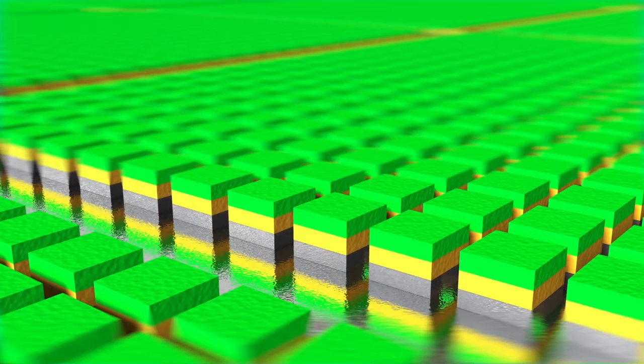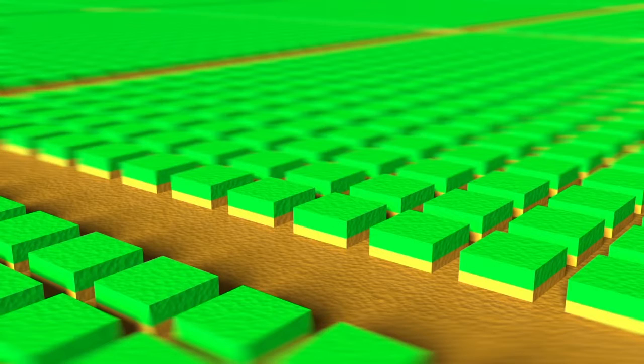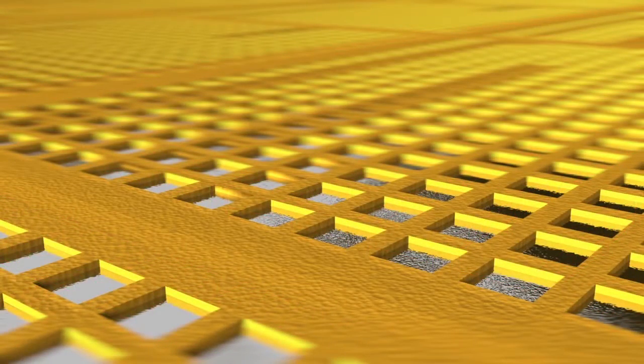Another layer of silicon dioxide is then applied, which will serve as insulation between the transistors. Etching and grinding processes expose the silicon underneath. Photolithography is used once again in the process of doping the silicon regions, for the purpose of protecting the regions which are not to be doped.